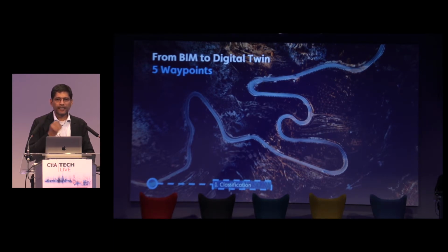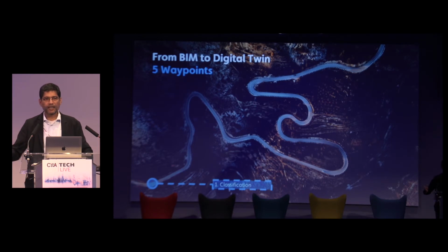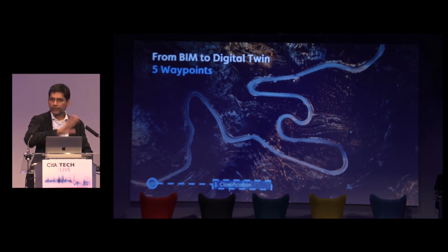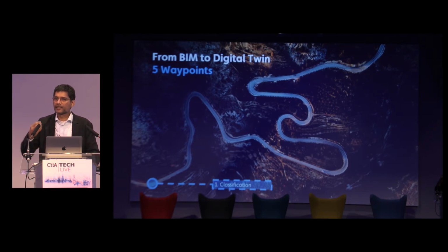Every single element in that model needs to be descriptive, needs to be expressive as to what it is. So classifications, we've got to start with making sure that the models are well classified. Whether it's Uniclass, whether it is Omniclass or Uniformat, doesn't matter, but it has to be done in the context of how it's going to be consumed. Because if the data is not structured, all of our beautiful visions and futuristic views will simply not happen because the systems, the machines, will not understand what's in the model.